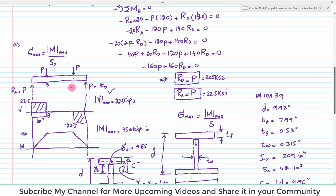And again you can see between point B and C there is no force, so shear force will be 0. Clear? But at point C there is a load of minus 22.5, so it will go down. So this will be your shear force diagram for the beam.